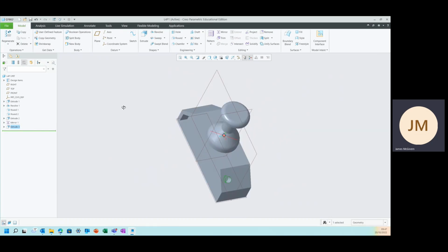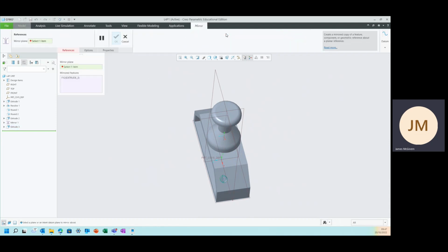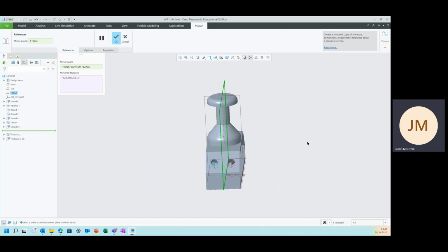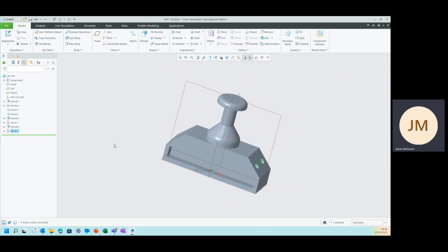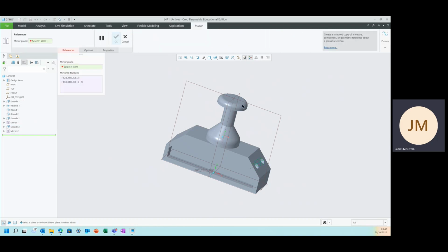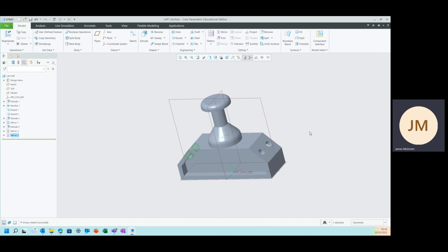And that hole is selected. It's green, you can see there. So what I can do now is just mirror that hole, send it around here, around the center there like that. And you can see it goes over there. And I can then, if I want to, mirror those two holes over the other side. I don't have to remake them. So I'll click on extrude, put down the shift button or the control button, and click on the mirror as well. Go up here to the mirror tool and click on this plane here, and the other two holes are sent across there, and that's it. Now that's slightly different dimensionally to what I have on the sheets, but that's showing you the techniques.